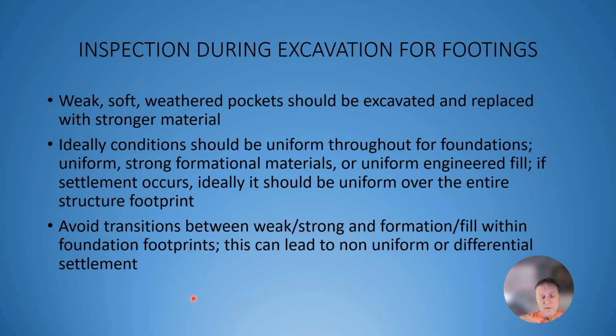So, for example, if you have a native soil, you might want to excavate 3 feet down and then replace all that soil with uniformly compacted fill to take away any variations in density from a natural deposit. So that gives you uniform strength.